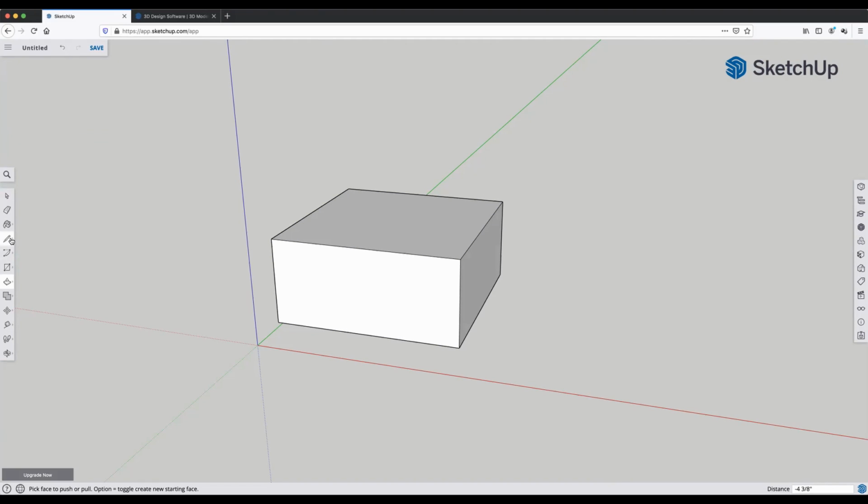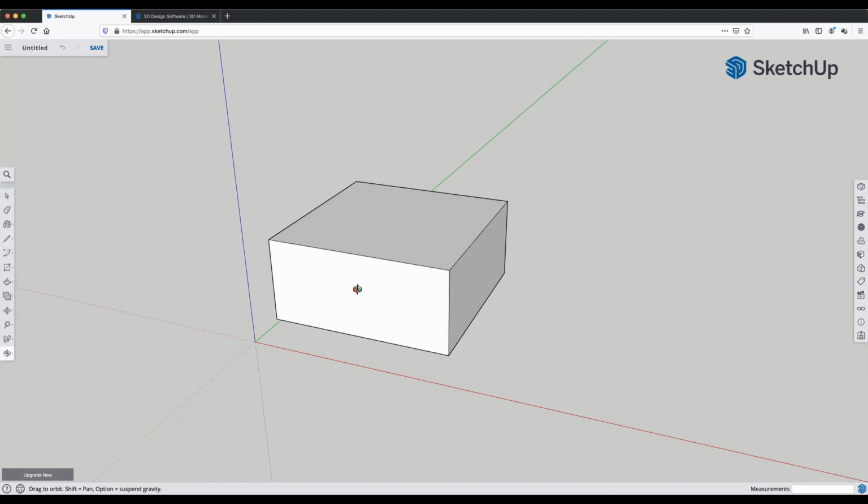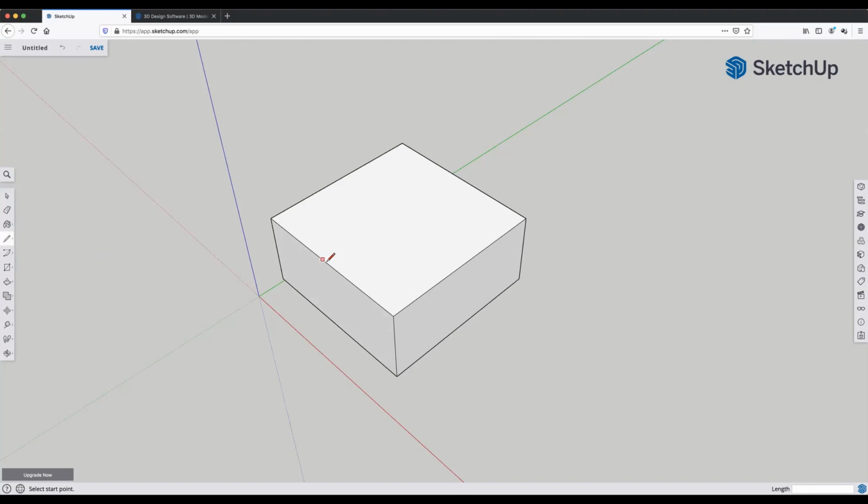So do another little demonstration here with the line tool. So a few choices above that is our line tool. We have a freehand tool, which I'll go over later. But if you select the line tool, and let's see, I wanted to add a line to draw a simple house. I'm going to find the midpoint. So if you just move your mouse along the edge here, you can see that's our endpoint. And if we move, we'll get this blue circle, and that's our midpoint.